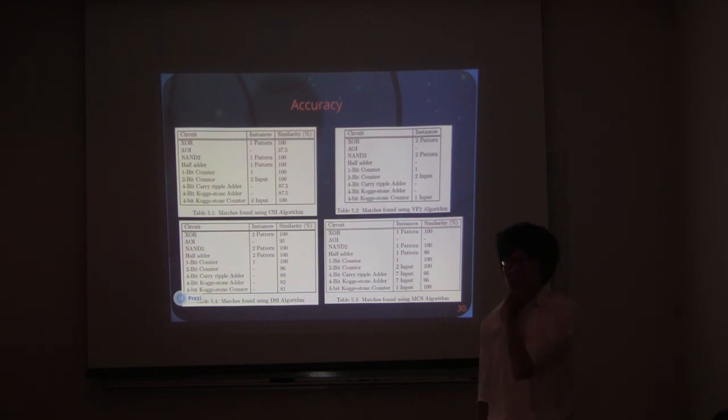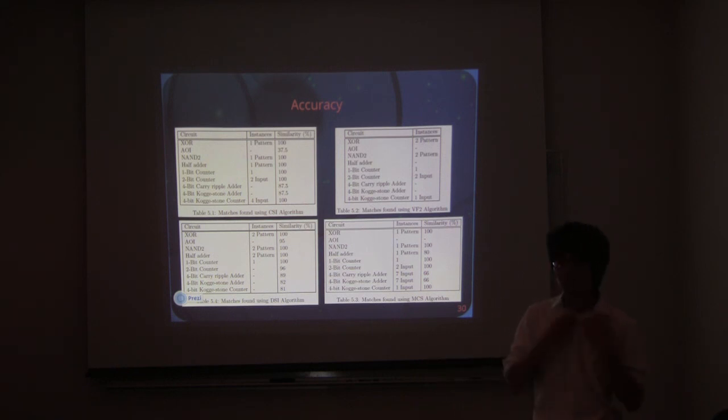Yeah. Okay. So that was something I mentioned in the functional part: just because they have different structures, the structural matching won't be able to pick it up, whereas functional matching would. But the other thing is, one possibility is to try and come up with all the possible combinations of a specific pattern. Or normalize the circuit to begin with. Yeah. Look for these patterns and convert them all to NANDs. Okay.